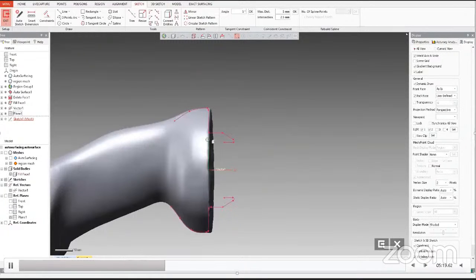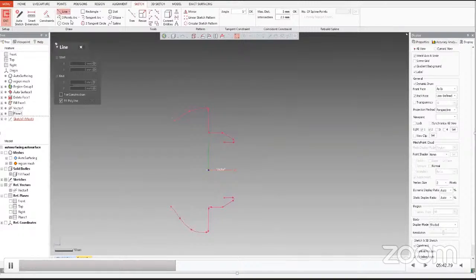Now this is a solid body as well. We can also see it is completely at the bottom of that solid body. There is also the revolve feature. Since we want to make the revolve feature, I will create the sketch in a way that it intersects with the solid body. I will tell you the reason why I am going to do it like that, because it will give me a single solid body in the end. There won't be two separate solid bodies.